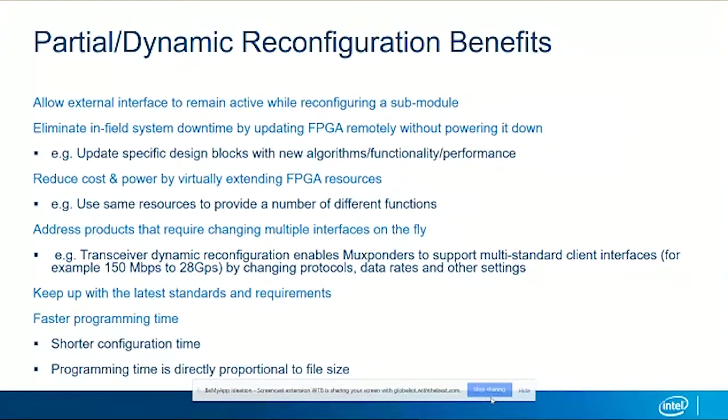offline. Effectively, you can reduce the cost of the FPGA because you're really extending the FPGA, and that if you, based on a certain condition, you want to configure a block to have different functionality, rather than having all of those blocks already in a single FPGA, you can have some of that functionality stored externally, for example, in a flash or on a workstation, and then update them as needed. You can also put the device into low power mode, in that while a particular block of the FPGA is not being used, it gives you the option to put it into a low power mode.